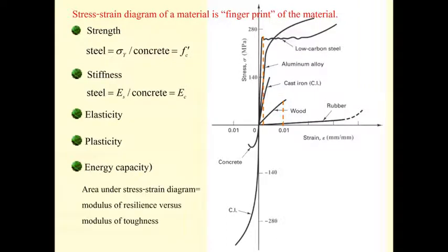Okay, for the plasticity, that's how the material can deform beyond the elasticity. And the last one is the energy capacity. We measure the energy capacity by the area under the stress strain diagram. The material that can consume large energy can tolerate high impact force.